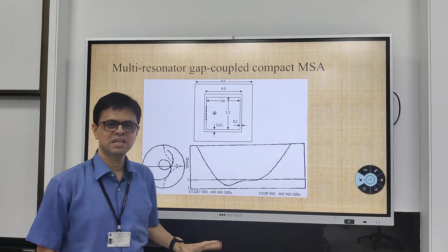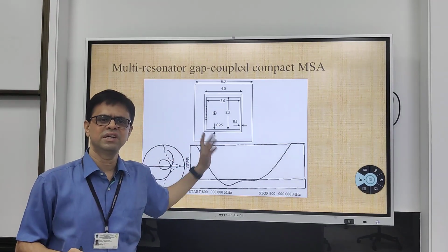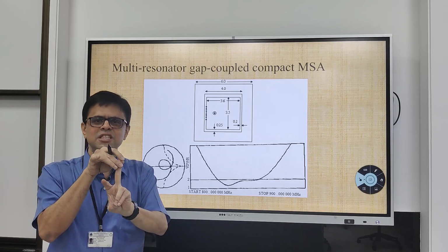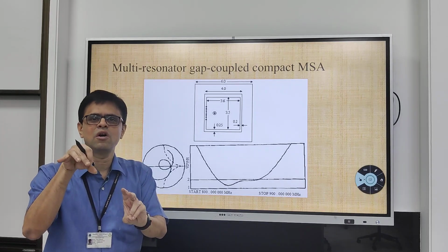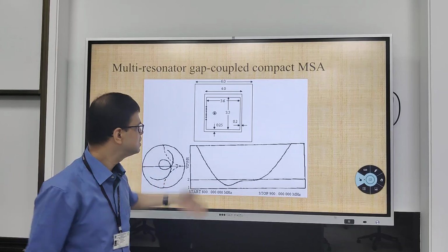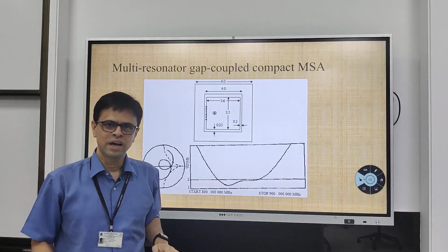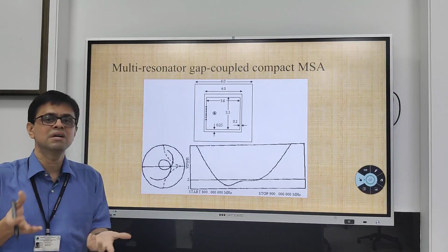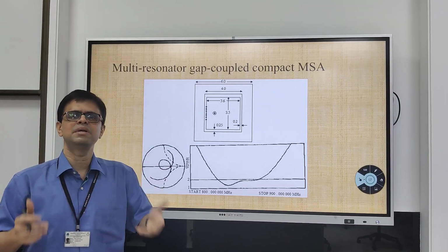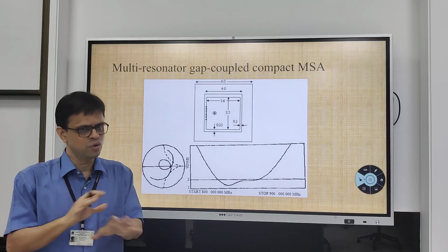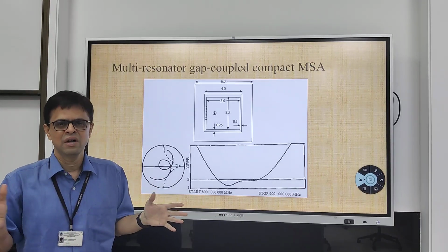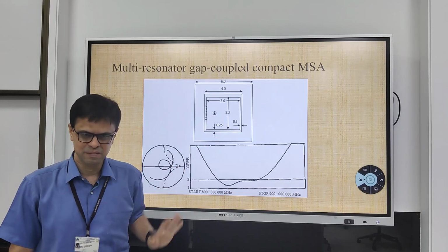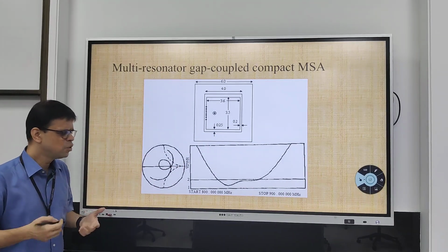So here in this case, or in the previous configuration, I have not increased the total patch area. I am using the empty space which is present inside that compact antenna to put additional patches and increase the bandwidth. And then overall bandwidth is increased. In fact, this configuration helps to increase the gain also, because slight increment in the aperture area is also achieved. Of course, not in the line of 3 dB increment, but it does give me some increment in the antenna gain. But these are some novel techniques which are there.